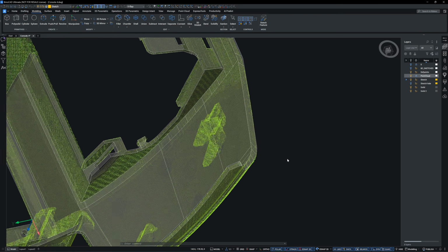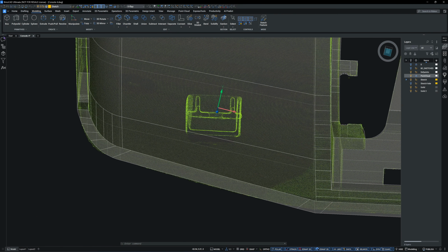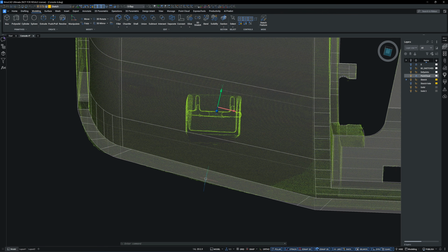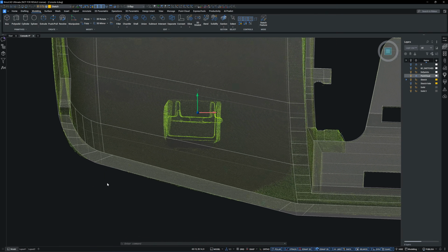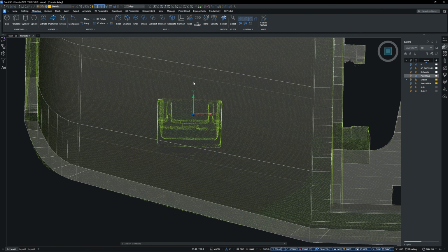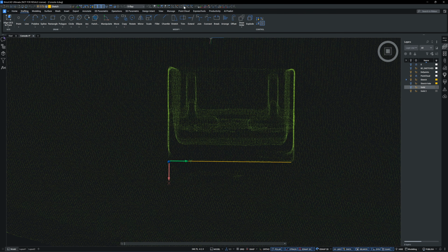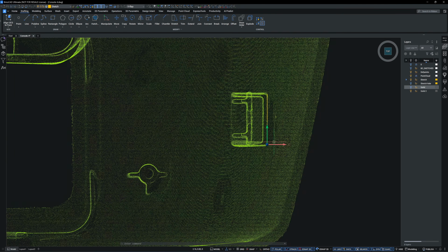Now moving on to the back side, there are several mounting clips to model here. The clips point in different orientations. To determine the correct extrude direction, I adjust the viewport until the point cloud wall aligns, then use a UCS view to set the sketch plane. I also move the UCS to the required depth by snapping it onto the point cloud.